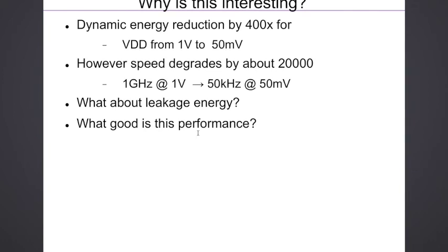Assuming that eta, which is the ratio between the depletion capacitance and the oxide capacitance, is the same for both the PMOS and NMOS. Is that so? Are they the same? That ratio depends on the ratio of the gate capacitance to the body capacitance, and the body capacitance will depend on the doping level. So they need not be the same, but they will be very close together.